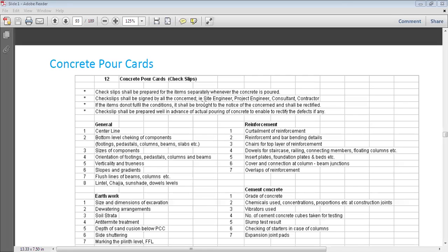Okay, so please be attentive in such cases. Whenever shuttering work is going on, you have to observe how the laborers are doing the shuttering work. There should not be a single percent chance of a gap. If there is a gap, definitely your concrete will get hampered. That water will percolate from the concrete, and you know what remains. So while shuttering, such care needs to be taken. And for the shuttering, you also need to take the checks.